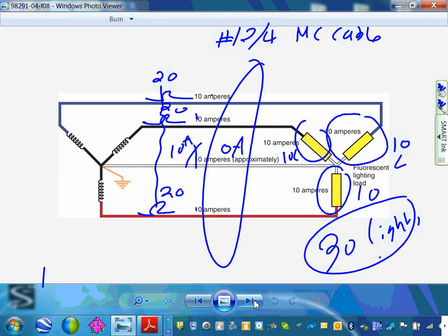3-phase and a neutral. Now, this is if the voltage is 208/120. We can put how many circuits, gentlemen? 30. Now let me up it for you. See the gravity of it. Let's use the same cable, guys, and use a voltage of 480/277. Same system. Change the voltage.